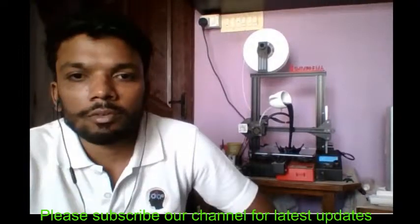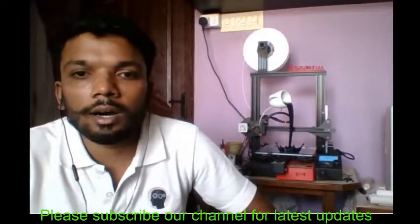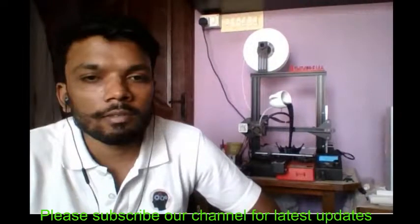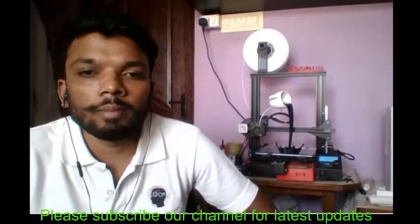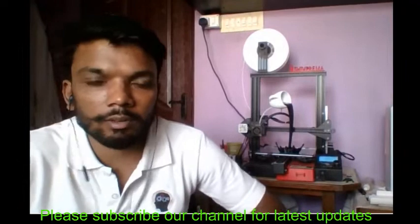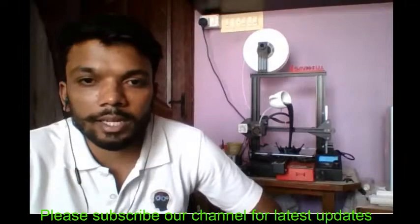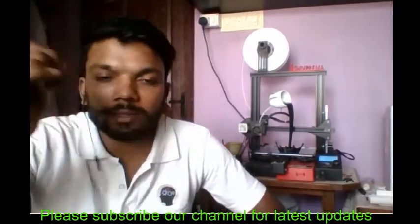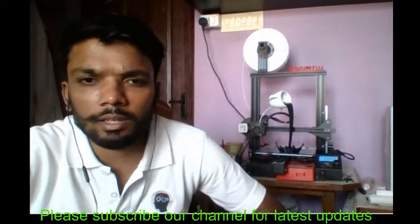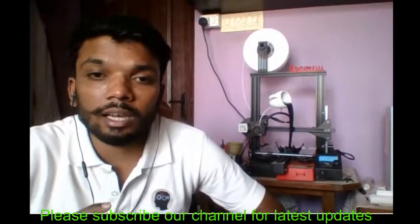Mostly, for making any outermost aesthetic parts, which are not that necessary, you can achieve them with FDM or something. But if it is an important component in a vehicle, it can be anything: even a bus, even a car, even a bike. The outermost component, the plastic one, can be done using vacuum casting or 3D printing. But there are certain limitations.